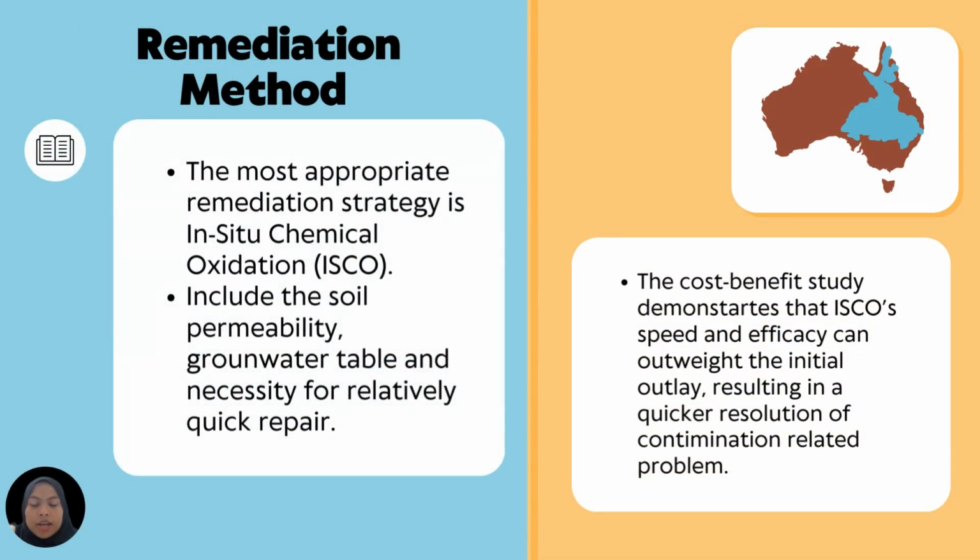Remediation method. The most appropriate remediation strategy is in situ chemical oxidation, ISCO. Factors include the soil permeability, groundwater table, and the necessity for relatively quick repair. The cost-benefit study demonstrates that ISCO's speed and efficacy can outweigh the initial outlay, resulting in a quicker resolution of contamination-related problems.